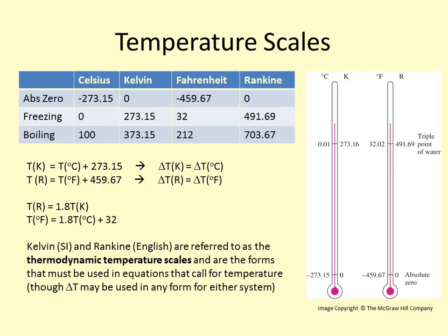The temperature scale, the most important thing to remember here is the conversions. So if you're converting from Celsius to Kelvin or Rankine to Fahrenheit, make sure in the problem, I think we had some problems with this on the last exam, that you're using the correct unit system. So if it's a problem where you're required to use English units, then you need to use absolute temperature in terms of Rankine, not in terms of Kelvin. So make sure of that.